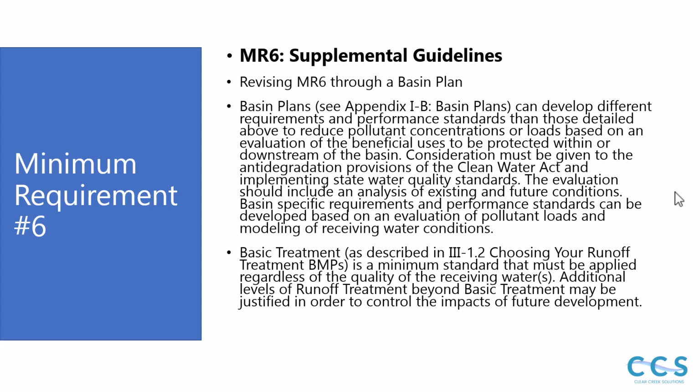Basin-specific requirements and performance standards can be developed based on the evaluation of pollutant loads and modeling of receiving water conditions. Basic treatment, as described in 3-12, choosing your runoff BMPs, is a minimum standard that must be applied regardless of the quality of the receiving waters. Additional levels of runoff treatment beyond basic treatment may be justified in order to control the impacts of future development.